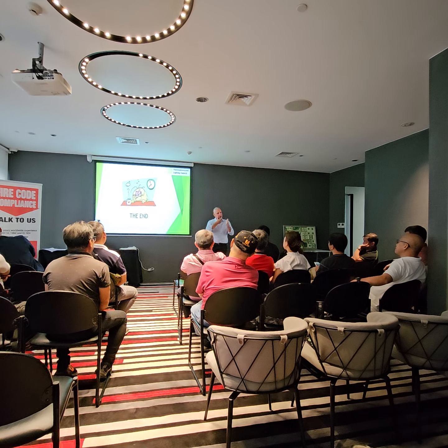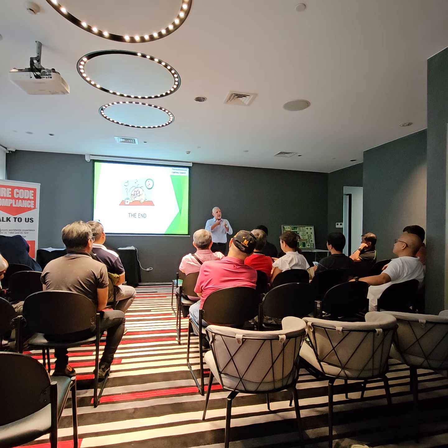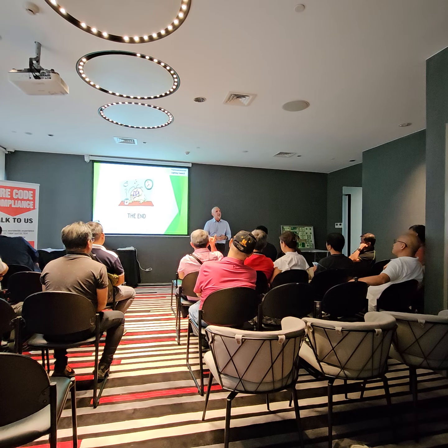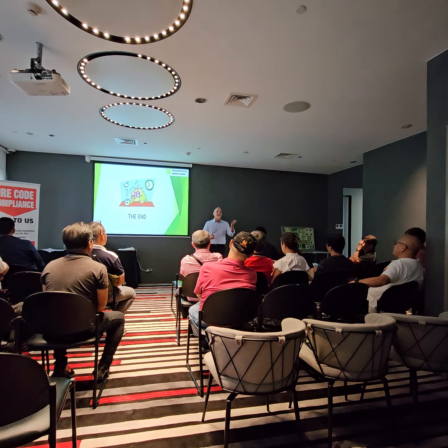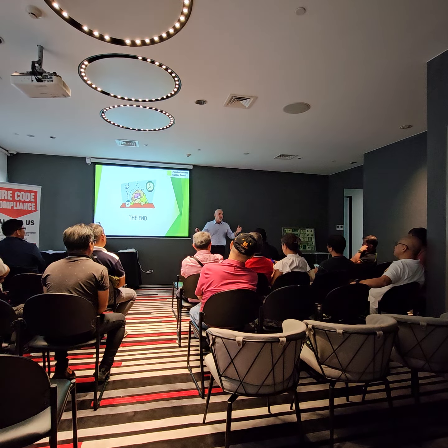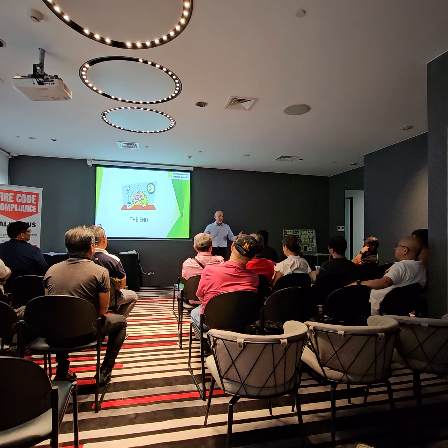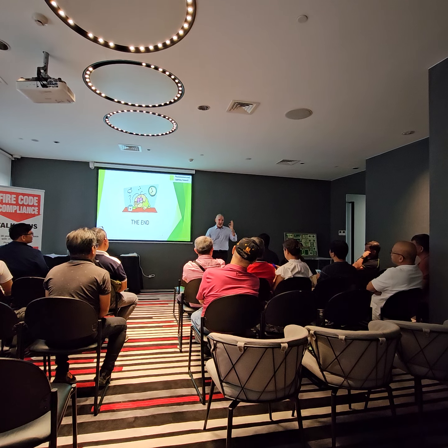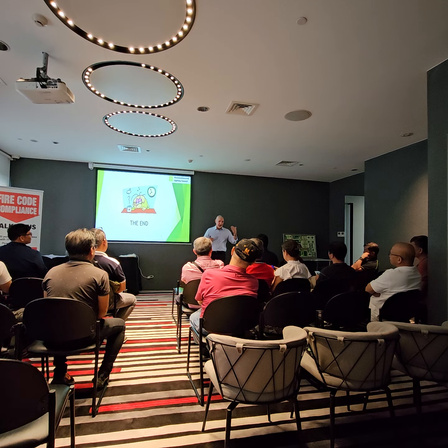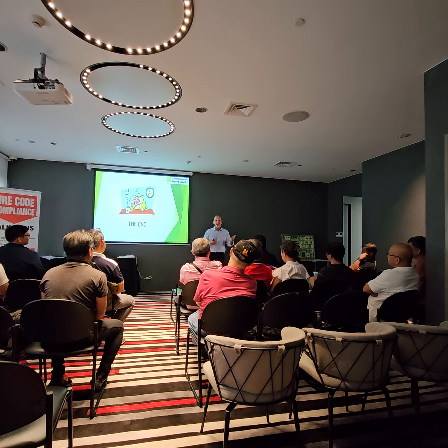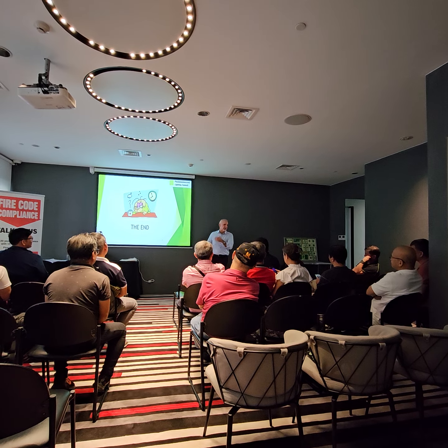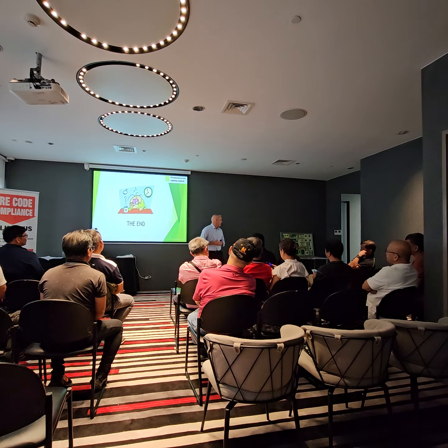It's simply to charge the photoluminescent sign or the material on each of the steps. It's assuming that you're in a totally dark, enclosed area and that the material is fully discharged, which takes 3 days. So it's quite a conservative way to measure it, but that's what it says on the UL sign.